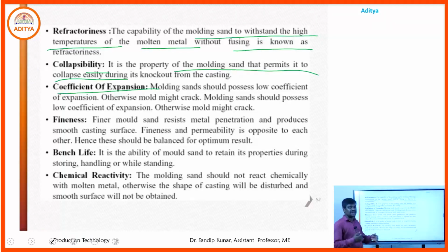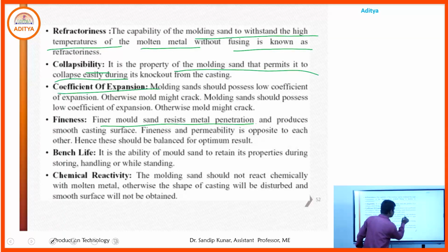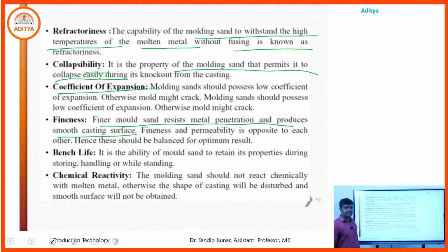Fineness. Finer grains of sand produce a fine casting product. Finer mold sand resists the metal penetration and produces a smooth casting surface. Finer grains produce a smooth casting product.